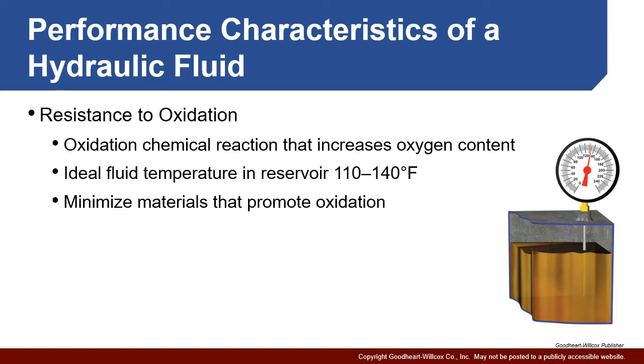The other thing about it is we find that the oxidation rate is very dependent upon contamination. Things like water, metal fibers that might come from wear, any dust in the environment. These all act as catalysts to oxidation and cause the oil to break down that much quicker. So we want to minimize the exposure of those types of materials to prevent the oxidation rate from going up. Essentially, we want our oil to last as long as it possibly can.